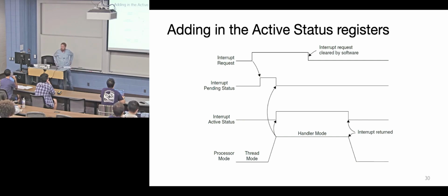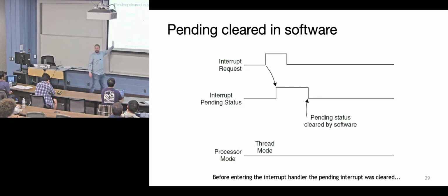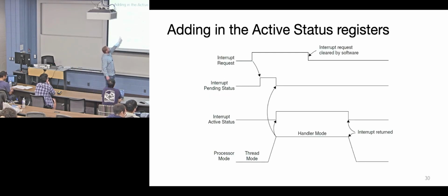Do we have to manually, like I know we have to clear the interrupt pending. Do we have to manually disable the interrupt request, or is that built into the software? It depends on the peripheral. You guys don't actually typically have to handle pending. That's just a weird slide. This past slide, the confusing one, is just an edge condition that says you can change the pending bit, but you don't have to. Software will deassert it, or hardware will do this, or the NVIC will do it. So you went to interrupt, you went to pending, and then by the action of going from thread to handler and stacking, it's deasserted. Once you become active, it's deasserted.